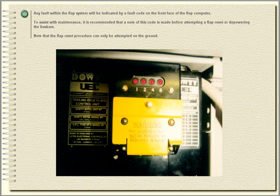Any fault within the flap system will be indicated by a fault code on the front face of the flap computer. To assist with maintenance, it is recommended that a note of this code is made before attempting a flap reset or depowering the buzz bars. Note that the flap reset procedure can only be attempted on the ground.